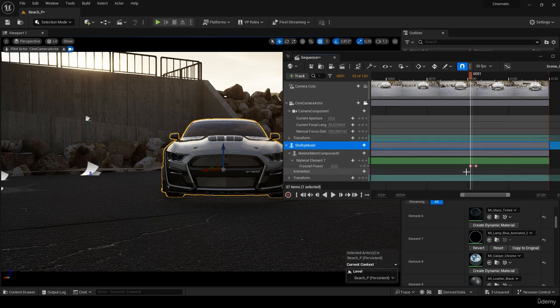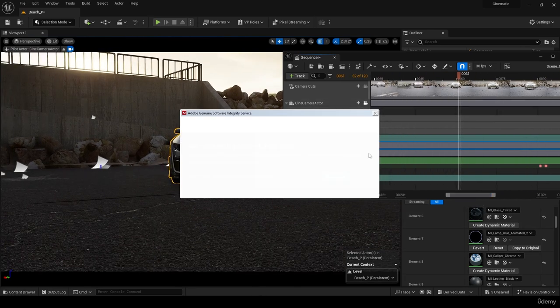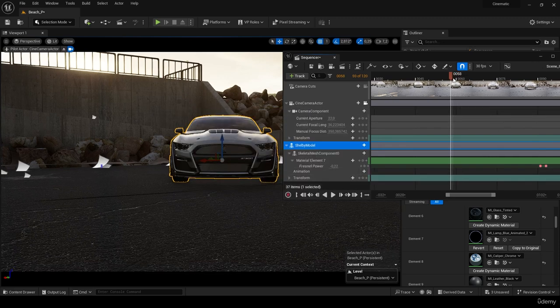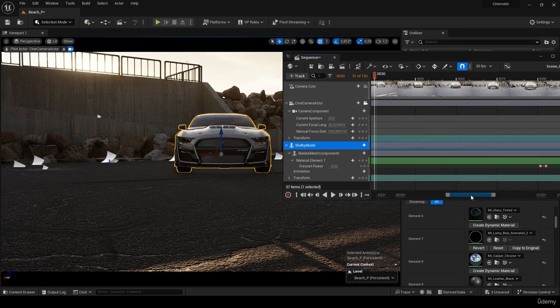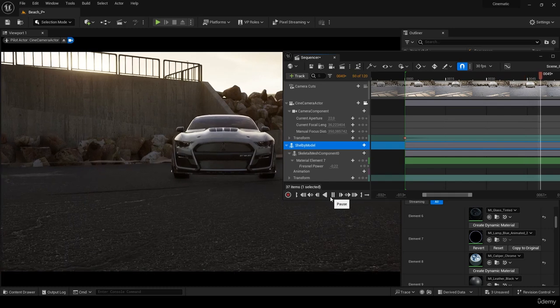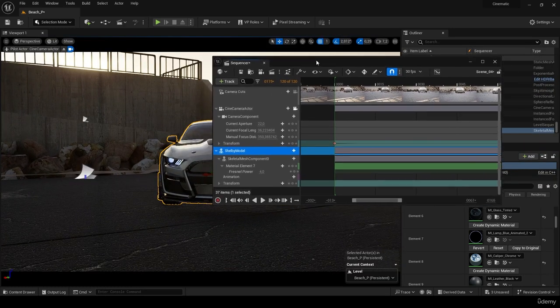So you have to be careful if you have other keyframes which are selected, because if a keyframe is selected and you make some changes here, it will apply to the selected keyframes, not to the keyframe you want to change the values of. For example, now we have this. Okay, now it's time to start from the beginning. Let's see. Perfect. It looks good, but it's slow.